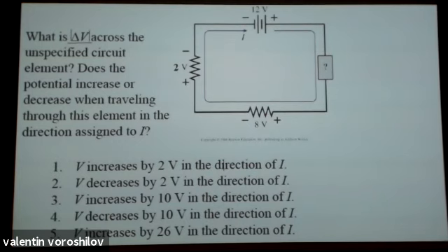The battery has a negative terminal. That terminal always can be set to zero potential. And relative to this choice, now this electric potential will be equal to 12 volts. And as we know very well, wires do not change electric potential, so electric potential remains the same all up to here, still 12 volts. And for now, that's all we can do with this side of the circuit.